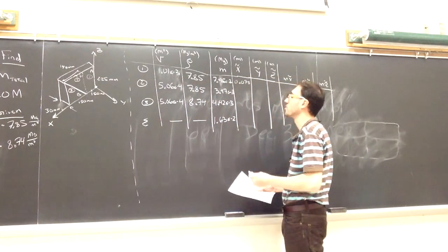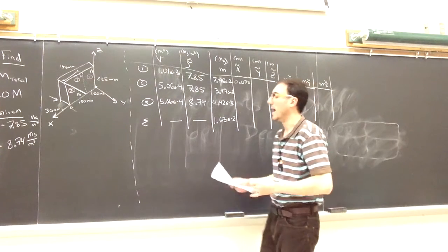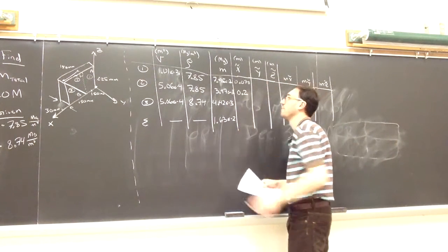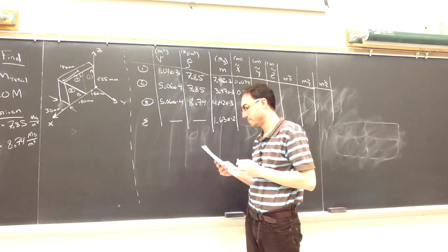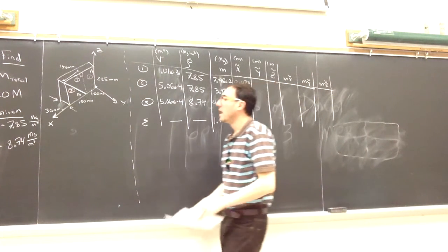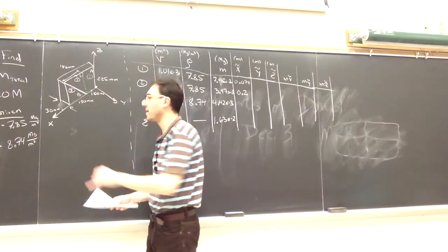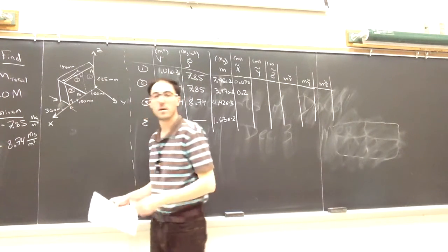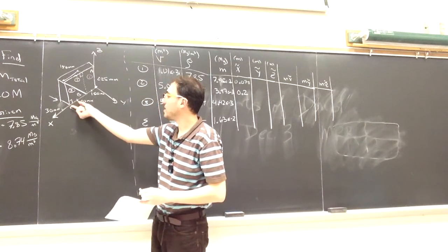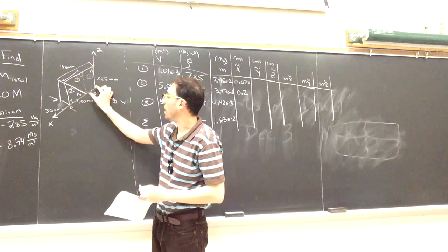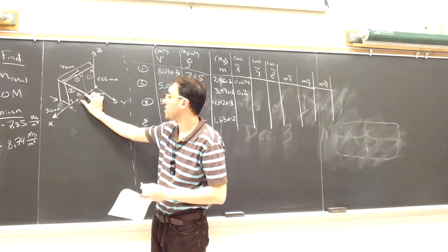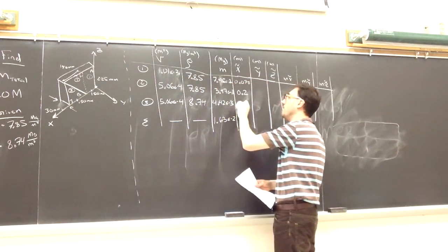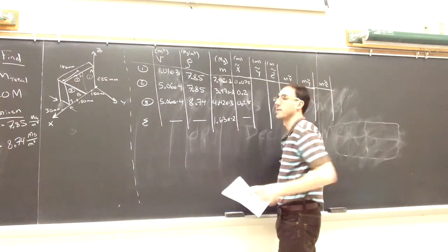So I have to go a total of 200 millimeters, so I get 0.2 for that shape. And for shape number 3, again, a right triangular solid, I have to go 1/3 of its base away from the right angle, so that dimension's 50. So I have to go 150 millimeters and then another 100 millimeters. So 250 millimeters or 0.25 in the x direction.